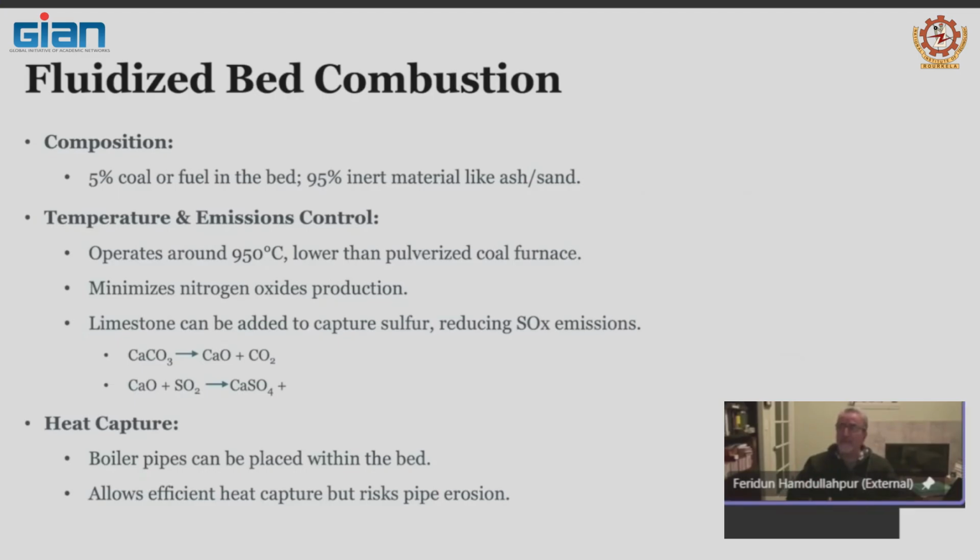They have to be maintained regularly because they are constantly grinding coal particles, and then they have to be fixed, replaced, and all of those. And they consume a lot of energy in doing that. There's no need for pulverizers in fluidized beds because the particle size is much larger, as we will touch on.